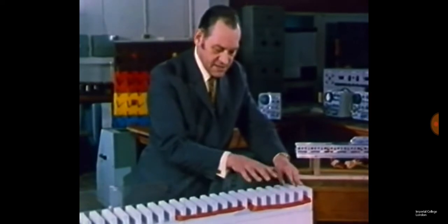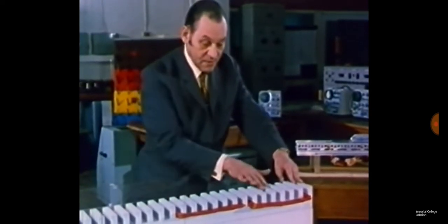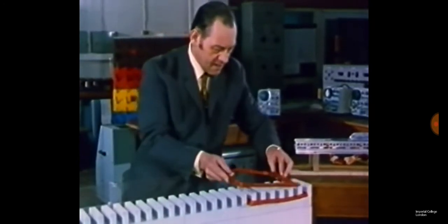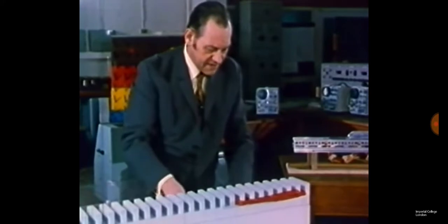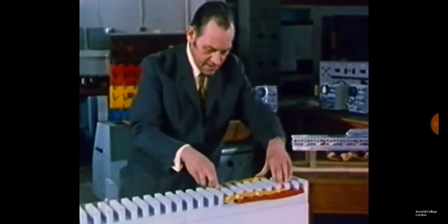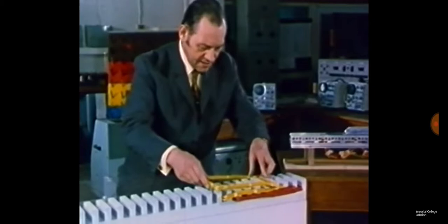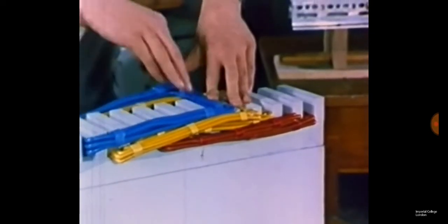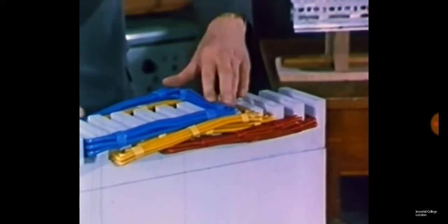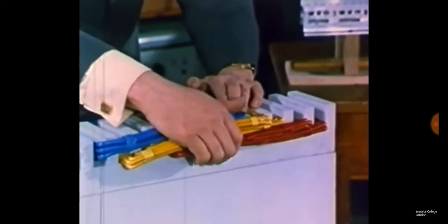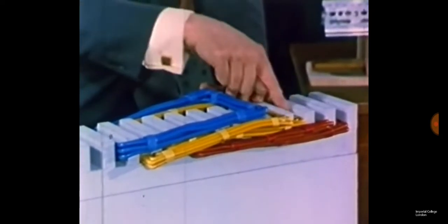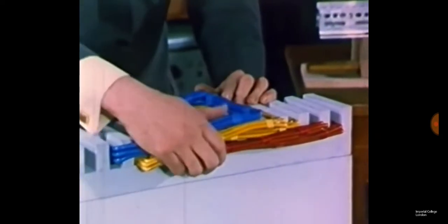But we're not going to leave all these slots empty in between, because that would be a waste of good space. So we're going to fill them up like this with coils carrying different phases of current as indicated by the colors. Try and fill up each slot. And now it's becoming increasingly difficult to get this end into the slot. This end will go in all right, but this one, you see, is getting very tight indeed, because we're building up a bunch of end windings there. Now, this is a great drawback, because this part of the current is the useful bit, producing the thrust. This part is just waste.